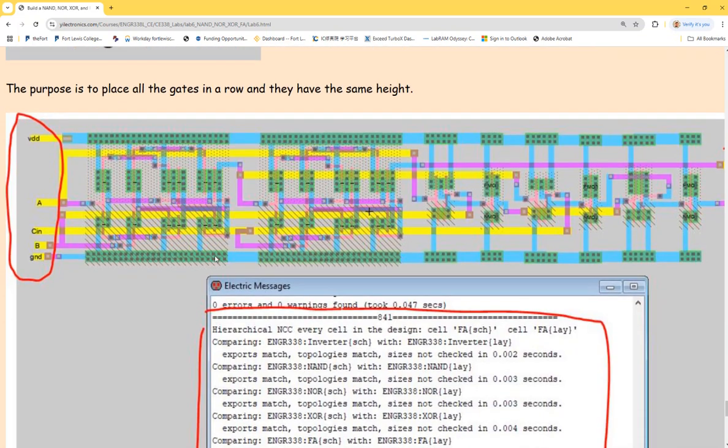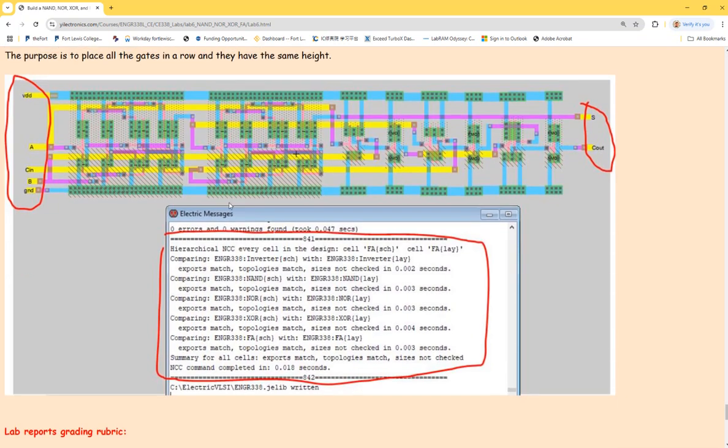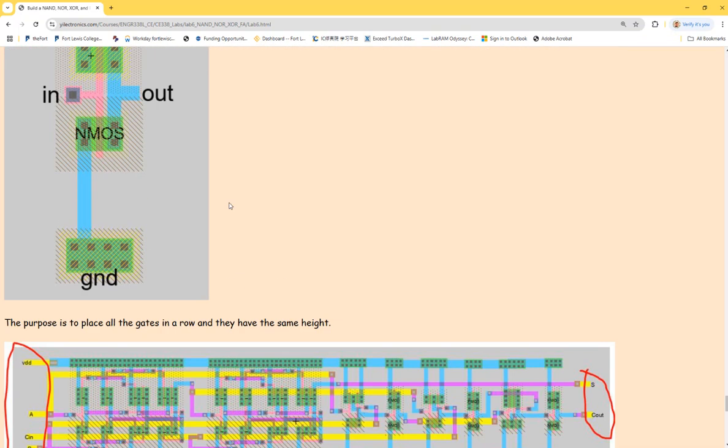Not that complicated. But eventually you will need a metal 3 sooner or later. If you look at this one, it's getting more complicated, and you will need metal 3, which is a yellow one over here. You only have 3 metal layers. So you can imagine if you have more metal layers, it's getting easier to finish the layout within a certain area, right? And more metal layers will let you keep your circuits more compact as well. You don't have to worry about any of the short circuits. You can make it more compact.